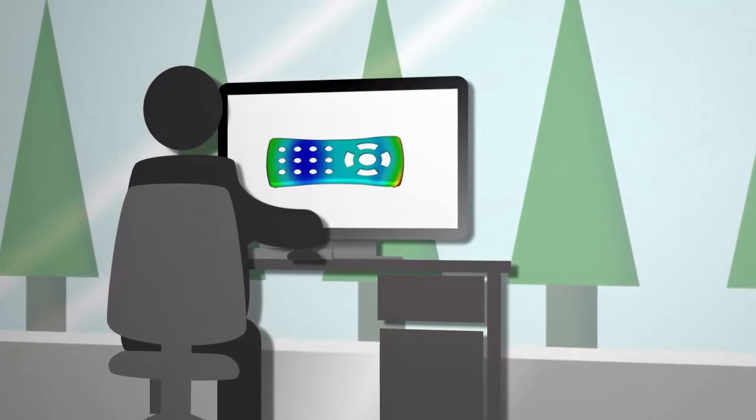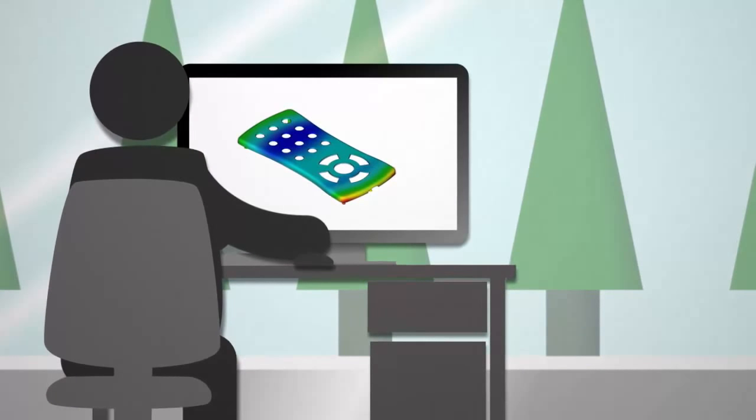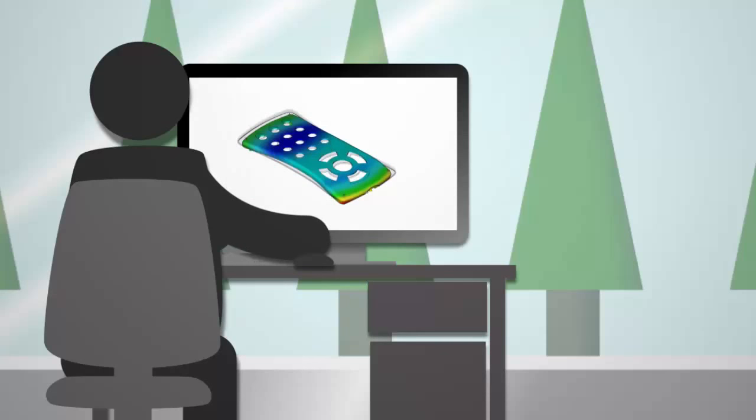You can minimize the effects of plastic shrinkage early in the product design cycle by using Moldflow Insight. By setting up and running an analysis, you can view deflection results, which help you visualize how far points on the part move from their original locations. If you have difficulty viewing the result, you can scale it so it's easier to interpret. You can also constrain the result to show shrinkage in a single axis.